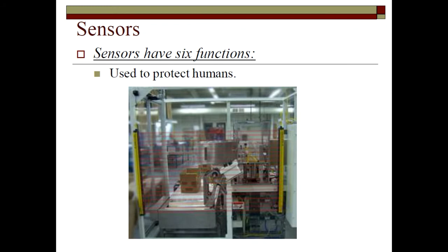All right, so even if it wasn't actually a person breaking through the light beam or some sort of true emergency, but just a wire got broke, vibrations and the wire broke or came loose from the terminal connection, all of a sudden, boom, you're going to go low, and now there's a problem. You're going to stop until you correct that problem. So that's why we wire those as normally closed.